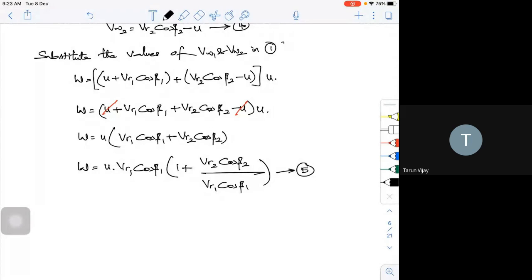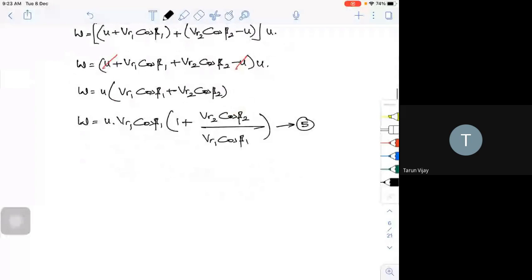So now look at this actually. This is a very general expression that I have. I told that for a Delaval turbine or any kind of impulse turbine, I can generalize this expression. If I take, for example, some CB, let me call CB equal to VR2 by VR1, or some K equal to cos beta 2 by cos beta 1.